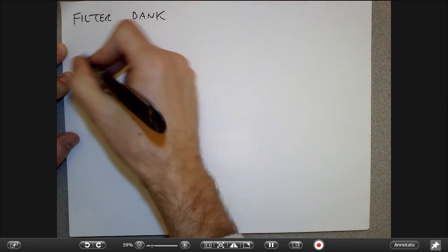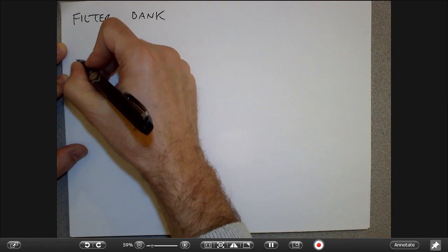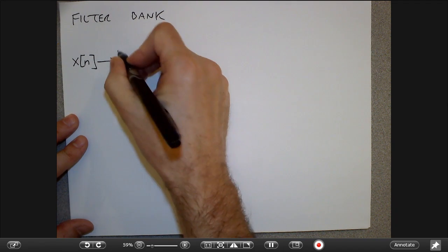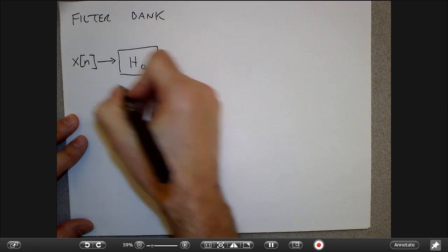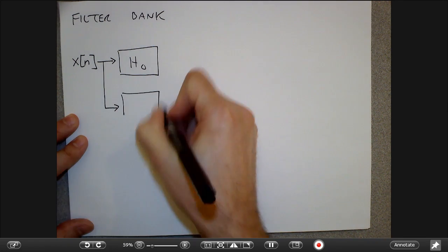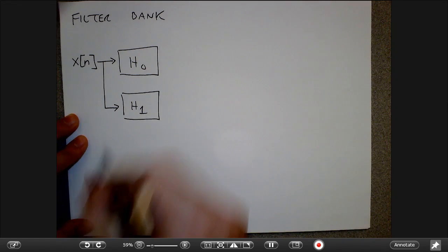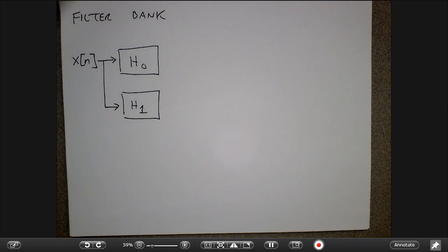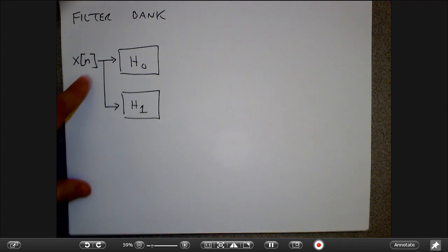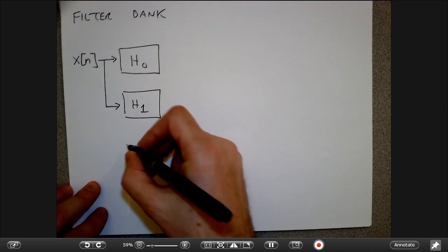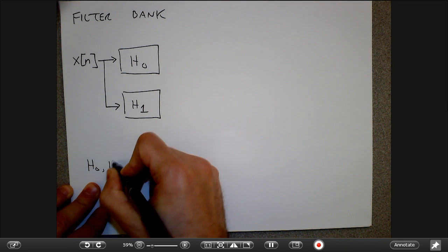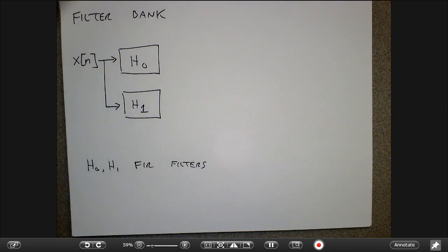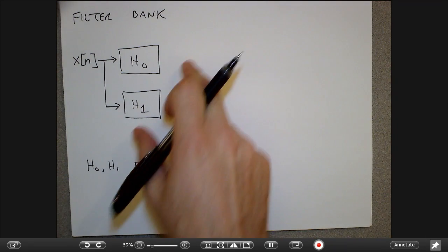And so here's an example of a simple 2-channel filter bank. And actually, I'm going to talk about a very particular kind of thing, which is called a perfect reconstruction filter bank. So the idea is that I have a signal that comes in here. I pass it through a filter here, and I pass it through a filter here. So again, here I've switched over to discrete time, right? And so let's suppose that I have n samples in my original signal, okay? And now I pass it through an FIR filter here and an FIR filter here. So if I pass this through these 2 filters, then each one of these is going to give me n numbers at the output, right?